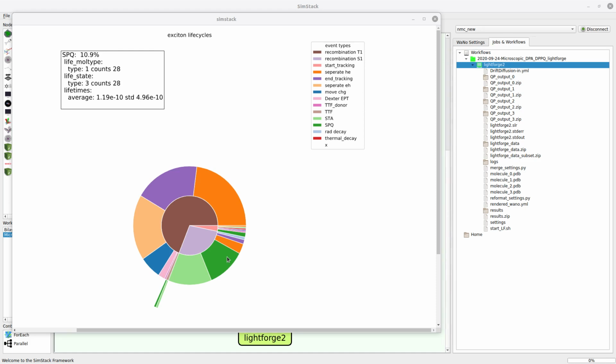So I think we can already speculate this OLED might have a higher efficiency if we would confine the excitons on one side of the interface and only to a few emitters, which also might not be accessible for charge, so might be charge traps. This might already give us some direction how to improve this rather simple device.